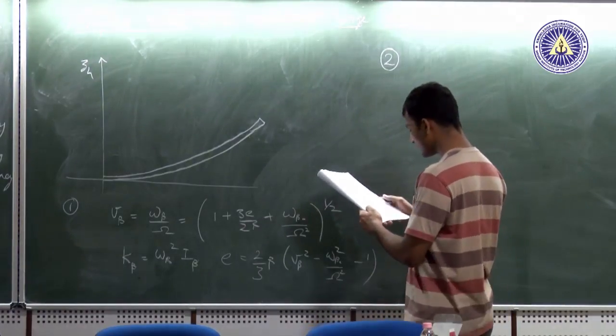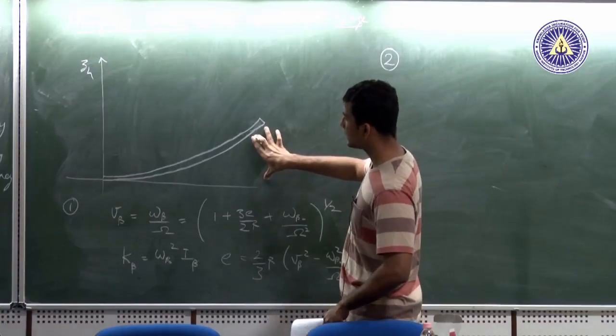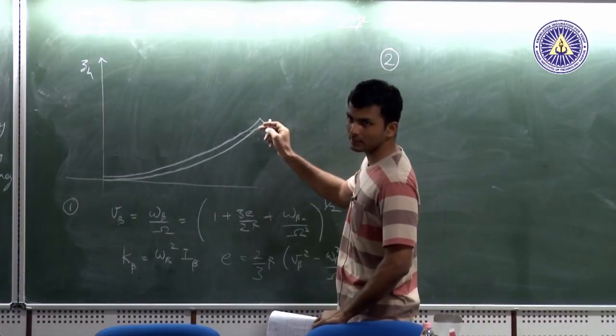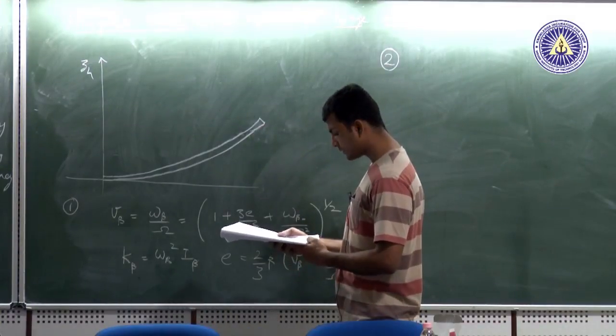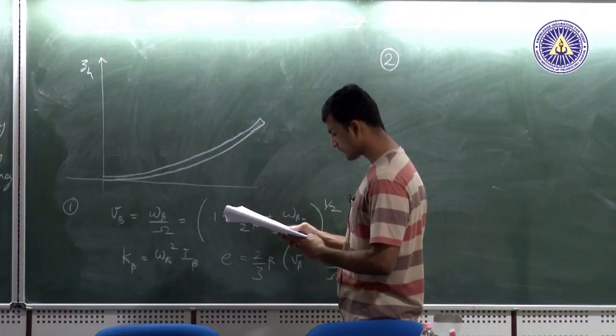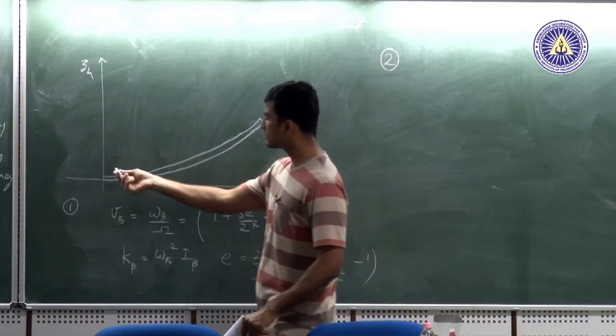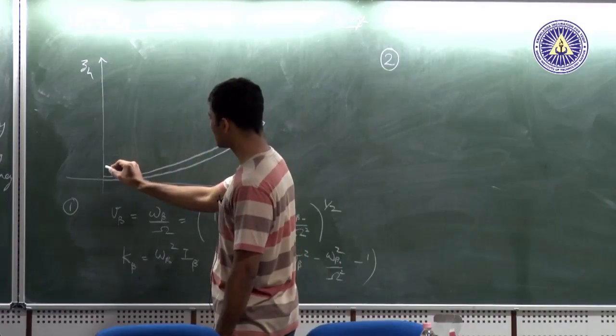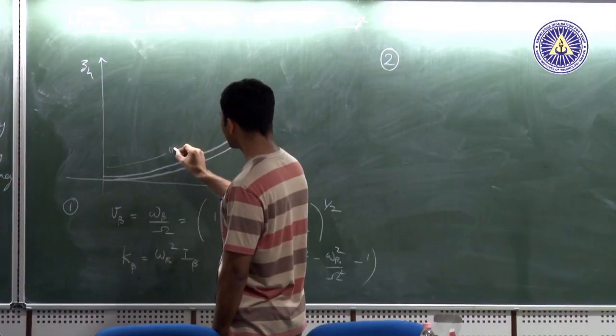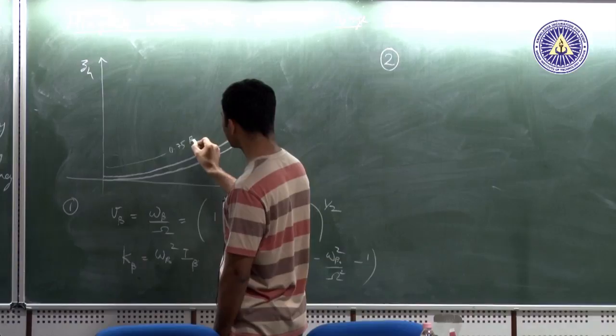So the second method is by studying the bending of this blade when you subject it to a steady static load. So what we do is that we look at 75% of this rotor length. So I will look at 0.75 times this rotor length.